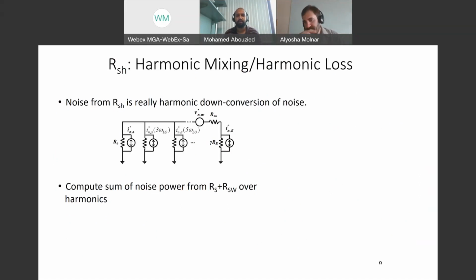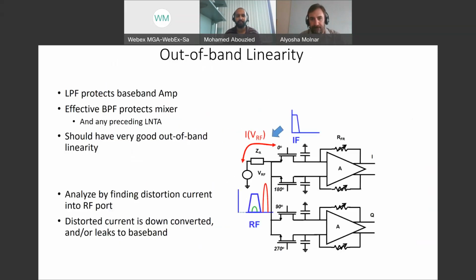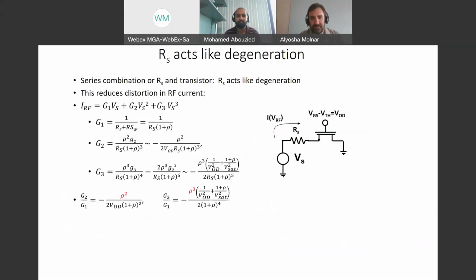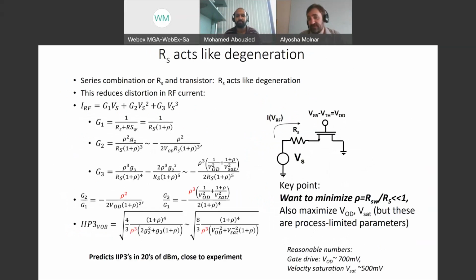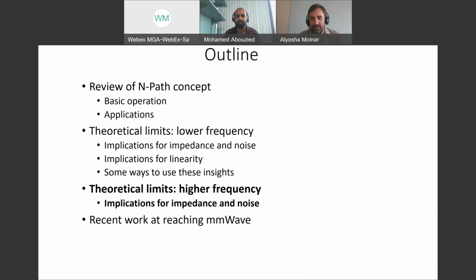I see. It's a little subtle, because you could be narrow band for your signal, but just high impedance out of band, and then you'd be fine. But if you show a low impedance out of band, then your noise figure gets worse. Oh, I see. So it's kind of harmonic tuning. Exactly. If you were to put in a structure that presented high impedance at the third and the fifth harmonic, for example, even if it was narrow band high impedance, that would still be beneficial. I see.